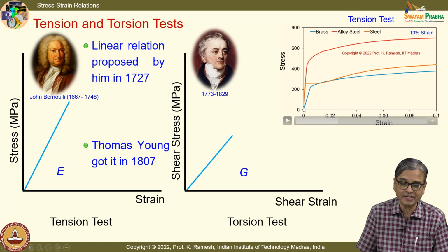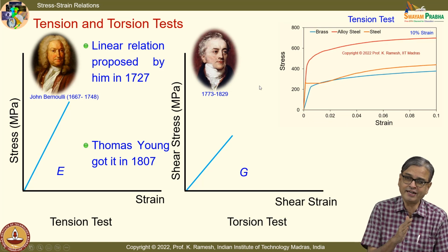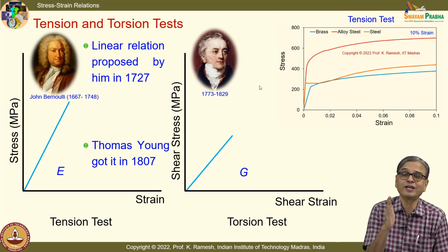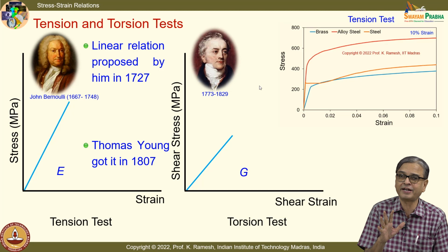If I have a linear elastic and perfectly plastic, you see it here. If I have a linear elastic and a bilinear curve to represent the plastic region, you have it here. And if I have a straight line followed by strain hardening, it is there. So the only trick is you confine your strain to a very small value where you see all these simplified material models. They are very useful.